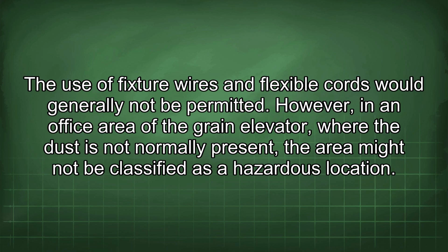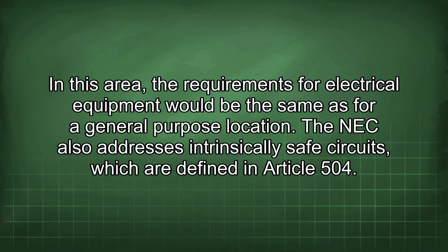However, in an office area of the grain elevator, where the dust is not normally present, the area might not be classified as a hazardous location. In this area, the requirements for electrical equipment would be the same as for a general-purpose location.